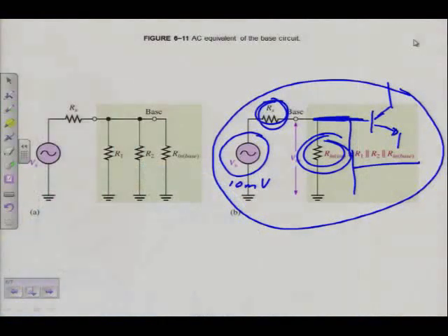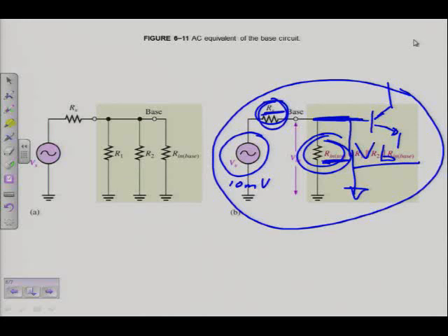Remember, I want the voltage between base and ground, so that is vb. If I know that's the voltage, then that resistance is on top of the line: R in total divided by the total resistance, which is RS plus R in total. That is the ratio for the voltage divider times vs, which in this case would be the 10 millivolts. And then I will find a voltage at the base less than vs, because it has been divided by the voltage divider.